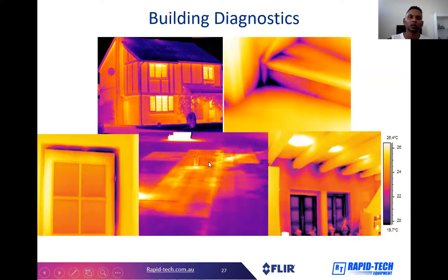All right, so we've seen there's a bit of a shift in the use of thermal cameras. We're seeing more thermal cameras being used in the building industry than actually, you could say, the electrical industry these days. So thermal cameras can look for damp areas or water leaks, missing insulation. It's a big application there, and that's purely qualitative analysis.